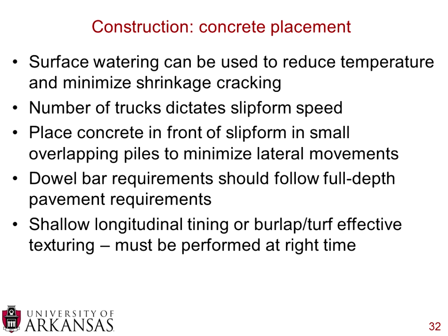As in any paving operation, asphalt or concrete, in concrete it's a slip form, in asphalt it's an asphalt paver. The number of trucks dictates your slip form speed. The worst thing you can do is stop your slip form, because then you'll have to cut a new joint and restart the whole process. So if you don't have a whole lot of trucks, slow down your paving speed to make sure that slip form is always moving forward.